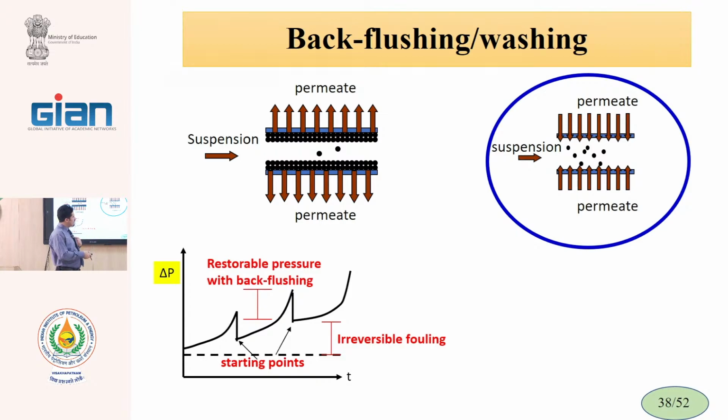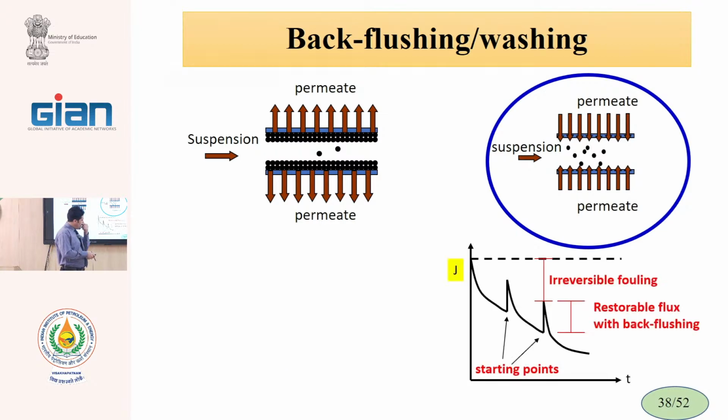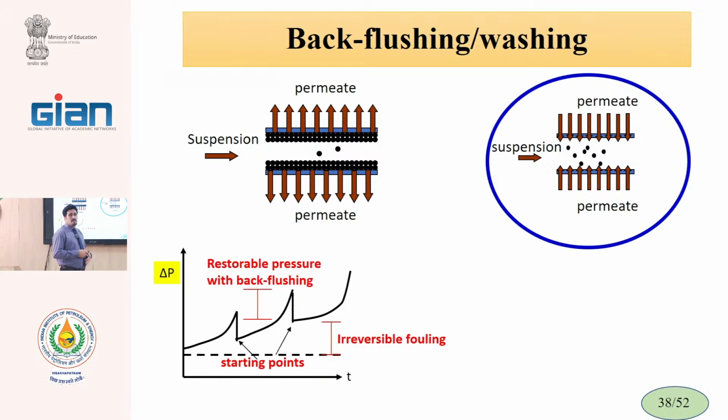We want every day to have 100 liters of product. But when flux is reduced, our product will be low. For this purpose, with the decreasing of the flux, for keeping the product amount at 100 liters, we increase the pressure.